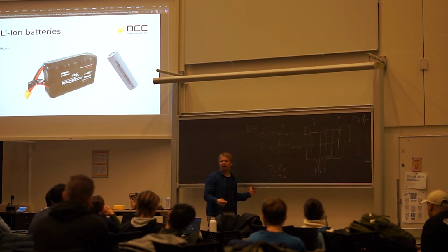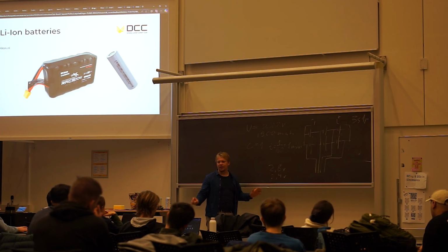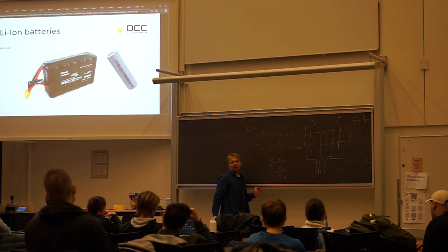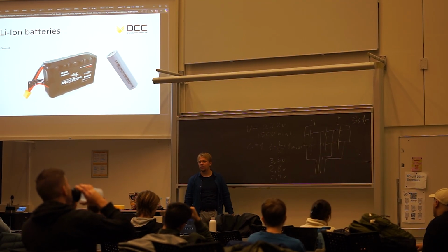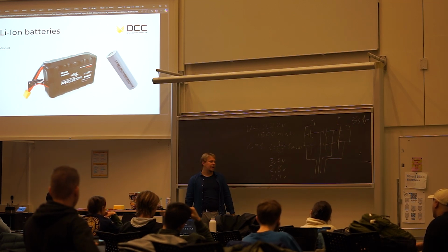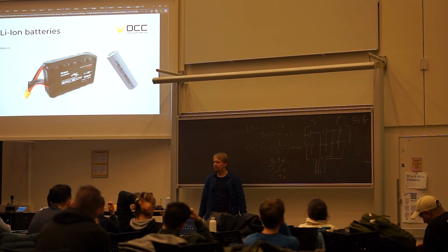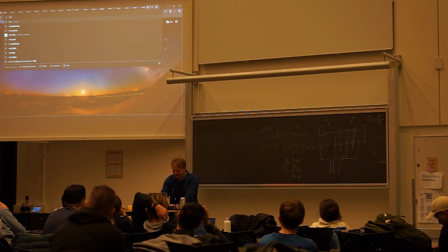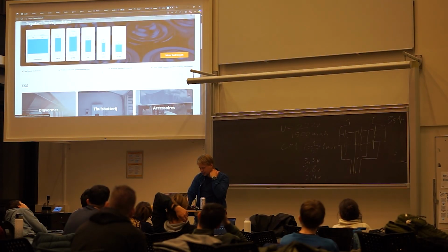Usually the chargers don't allow you to charge a LiPo battery if it sees something like that. It's going to be like, oh, a cell error. On LiPos, the golden rule is above 3.3. So 3.5, 3.3 is usually where you want to end your endeavors with the battery. If you go lithium-ion, it depends. You want to check the cell. I'll show you another shot. You can get really good cells here.